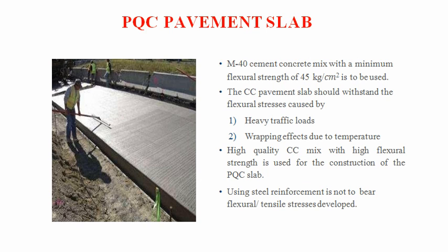Next, the PQC pavement slab. For the pavement quality concrete, we have to make use of the M40 cement concrete mix with a minimum flexural strength of 45 kg per centimeter square.